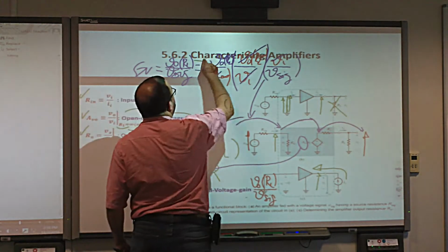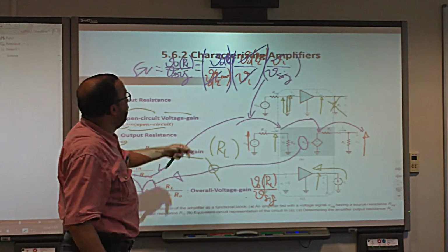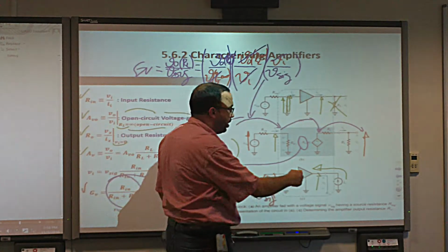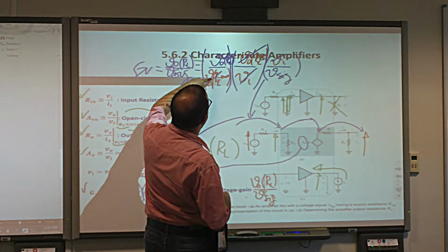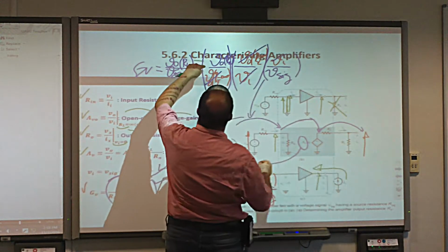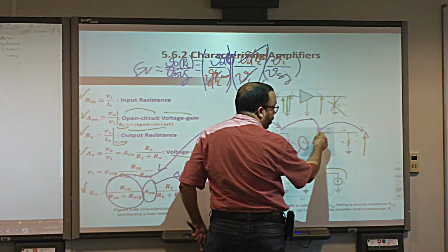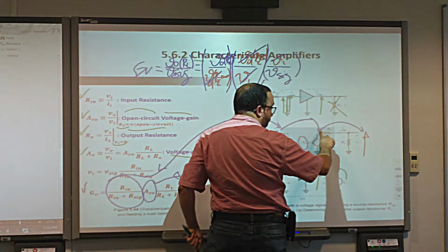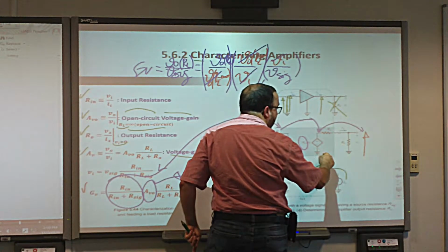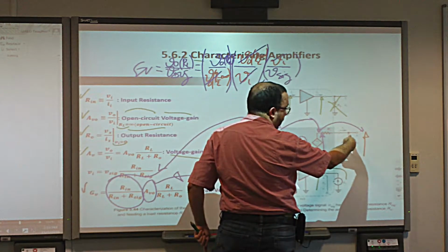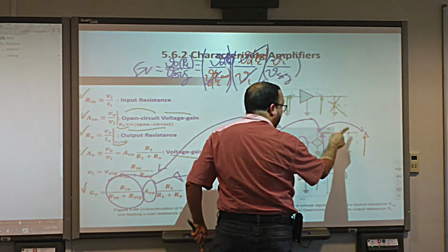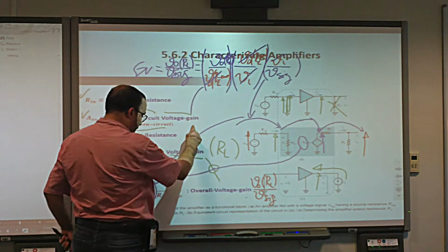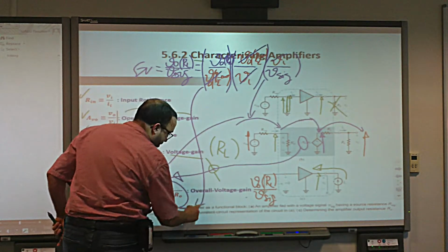Now the last ratio here, V out at RL divided by V out at RL equal to infinity. That means the voltage here when RL is equal to infinity, there is no current. It means the voltage here without having any current. And this is also a voltage divider, yes or no? So this divided by the whole voltage gives me RL divided by Rout plus RL, yes or no? And that is actually this last segment.